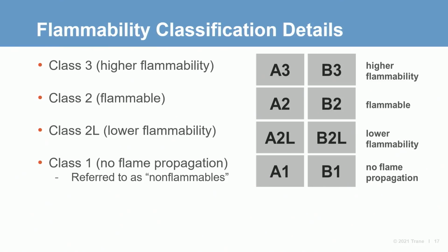It is important to realize that while Class 2Ls are more difficult to ignite, flammable refrigerants are still flammable, and an ignition event can occur in an uncontrolled situation. The search for new refrigerants, which have desired climate and performance characteristics, will result in the use of more flammable refrigerants, primarily Class 2L and Class 3. Many hydrocarbons are used today in small charge portable systems like refrigerators and freezers.